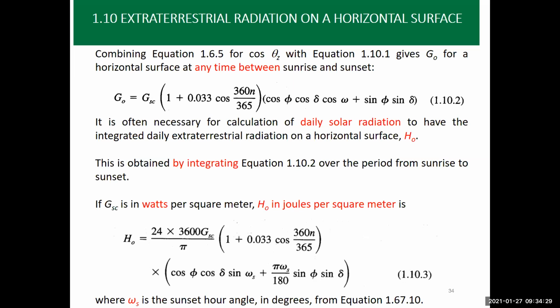Talking about laundries, for example. For a laundry, you need hot water always. So either you have a heater built in your laundry, which does not quite often occur, or you just bring hot water to the machine, to the washing machine. So the point here is that we're calculating how much is the load which is being required to be covered for every month of the year. We cannot do it for every day because this is tedious to do. And it's not worth it, because the accuracy that we are going to get on a monthly basis is going to be good enough.